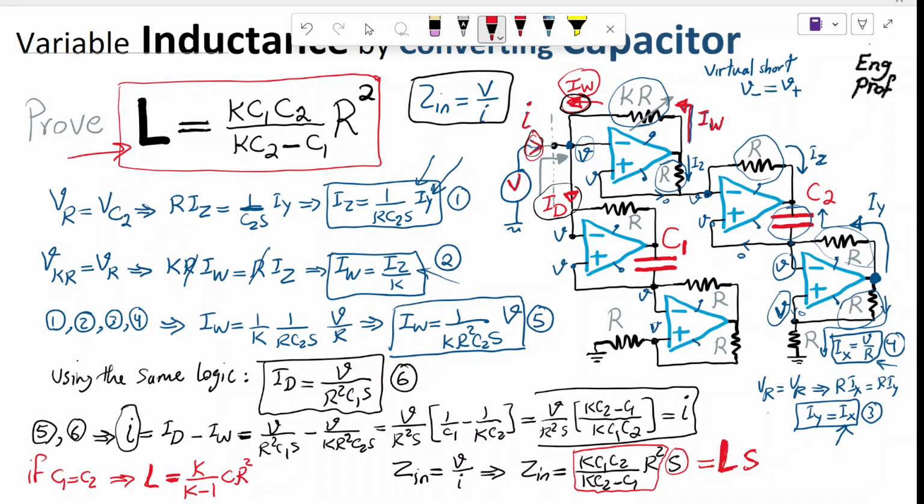So in that case, we have a programmable inductance that, using the potentiometer K, we can adjust, and actually, depending on the value of K in the potentiometer, it can realize a negative inductance or a positive inductance in the circuit, as long as the circuit is in practice stable. I hope that this is helpful.